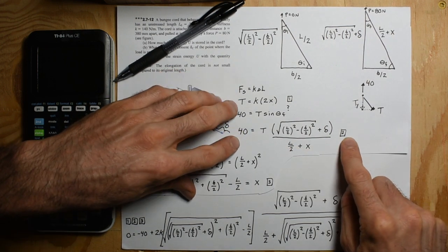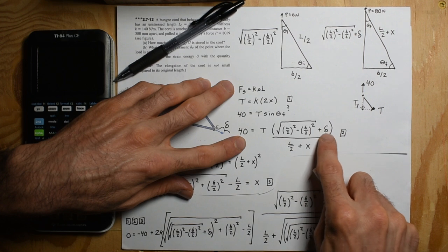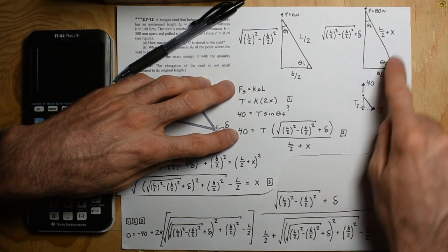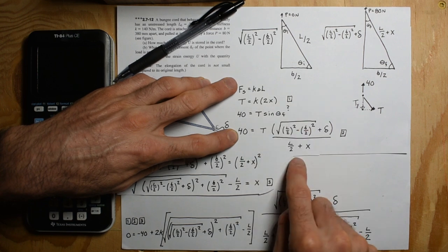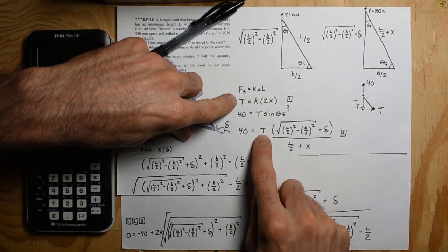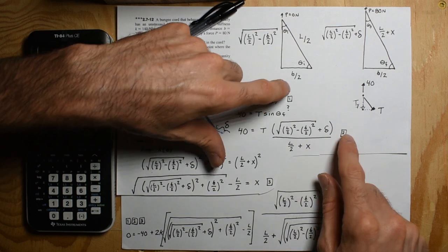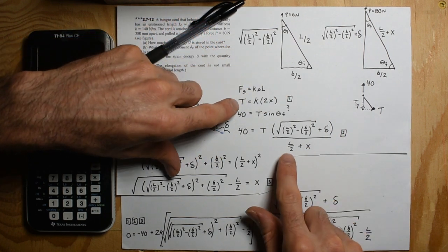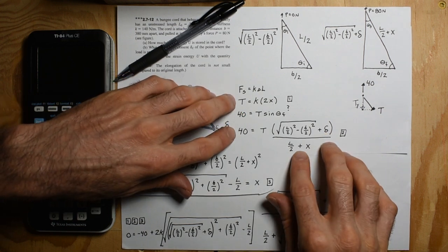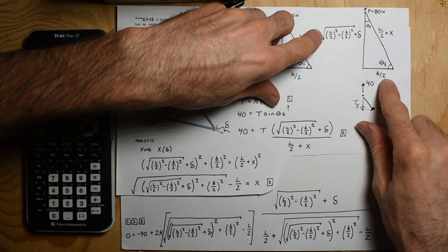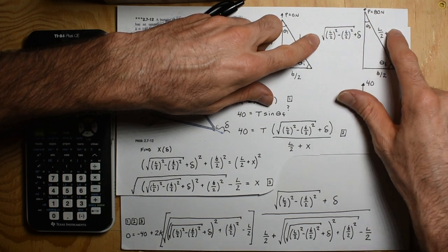So that's equation 2. This equation gets us very close, because it's a function of that delta, what we want, but it's also a function of this change in length of the chord. We're calling that x, and the actual change in length is 2x. So this has T, delta, and x. Well, the other has T and x, so cool. We have 2 equations, but we still have 3 unknowns: T, x, and delta. So now we use Pythagorean's theorem just on this final setup, and we say this squared plus this squared equals that squared.